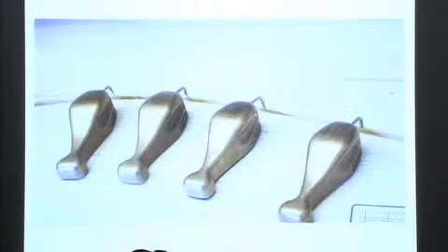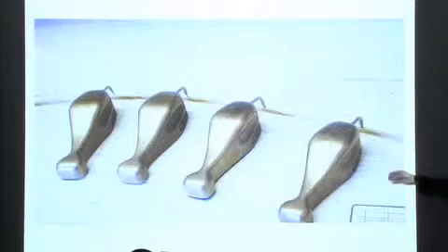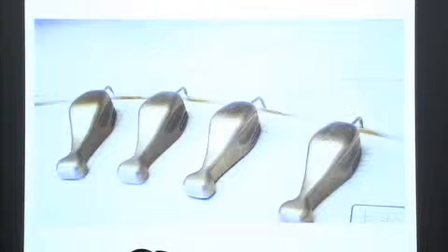My take on it as a student was this technology, which was used at the time for drafting curves, particularly, as you can see, sections through a yacht hull. And naval architects would always use these splining rods and weights, which they ironically made look like little lead whales. So to make the spline curve, in order to draw the yacht sections, they used flexible timbers, more latterly nylon rods, and they would weigh them down at particular points.